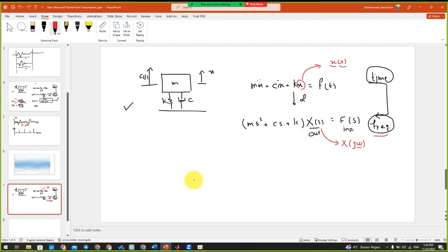Sometimes you drive with 30 kilometers per hour, sometimes 50, and sometimes 80, and through the time you will get it that at higher speeds, like 100 kilometers per hour, it's actually not going to shake your car at all. That's an example of how the behavior of x, the deflection in this case, is important for us through the frequency and not time anymore.